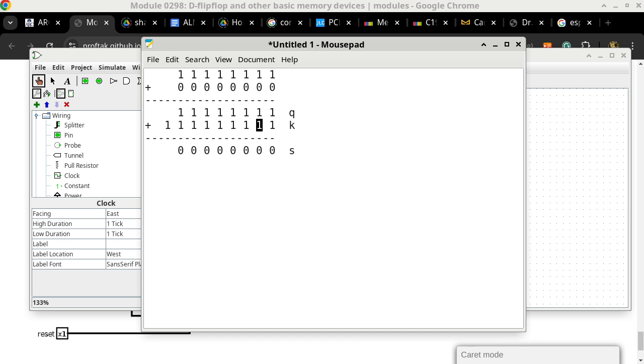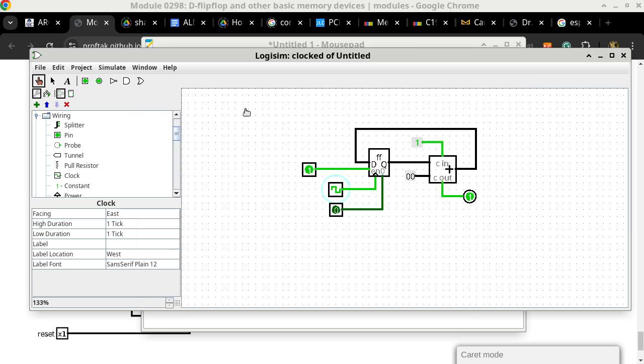So the timer is the opposite of what we just saw here. Imagine that instead of having an adder, you have a subtractor. But every time it runs out, it is reset to a specific value. So that's basically what a timer really is. It's a countdown timer. But when it resets, the value that you use to reset the counter is programmable. So now you can program the delay between the timer going off.